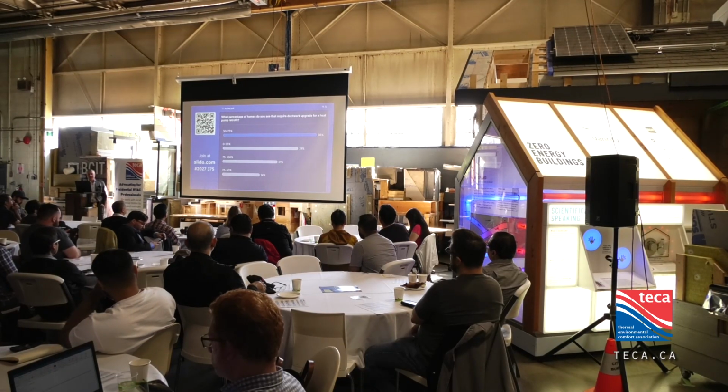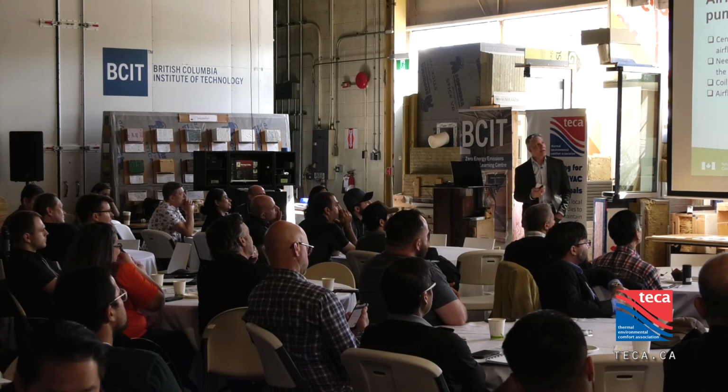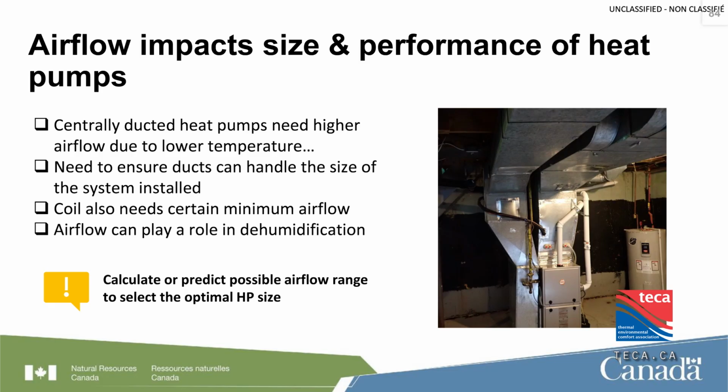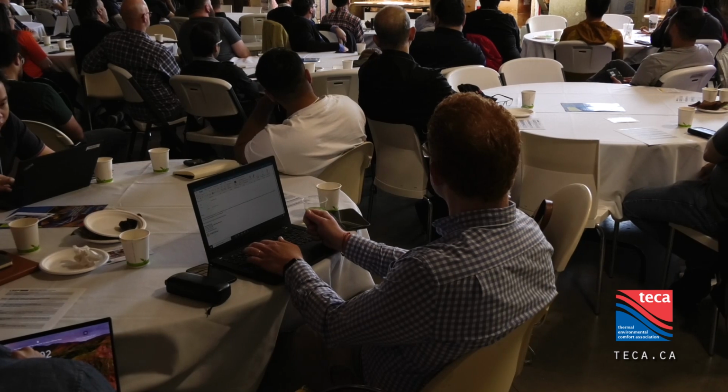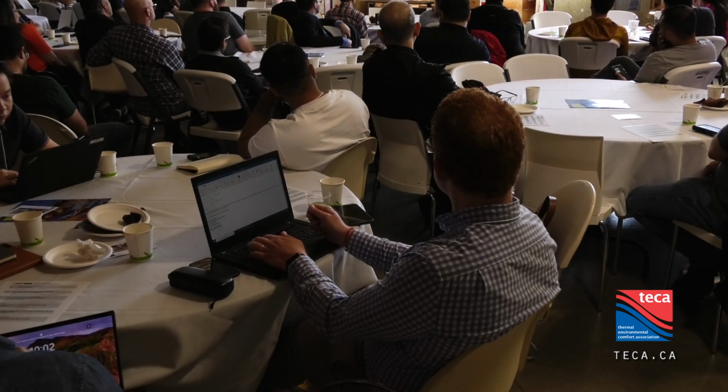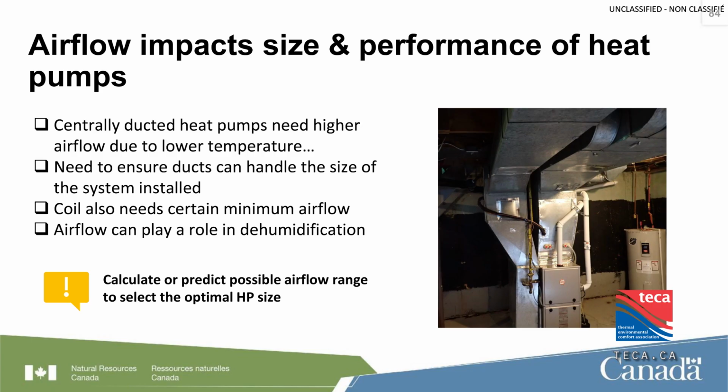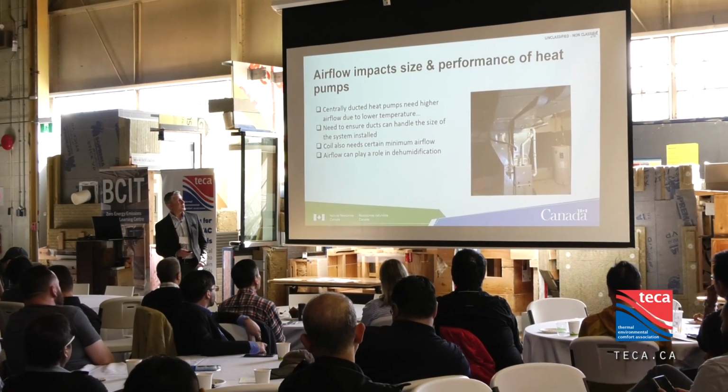Knowing the actual performance of the ducting system and what it can handle would be a huge benefit, not just above and beyond knowing what the design heating and cooling loads should be. So of course, centrally ducted heat pumps will be carrying air that's a bit of a lower temperature, so we have to be able to actually handle that. We need to ensure that the ducts can handle the size of the system that's actually installed as well. The coil also needs to have that airflow go across it so that we have the dehumidification happening. And of course,